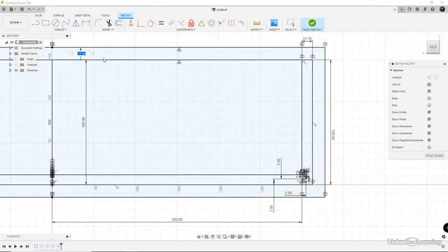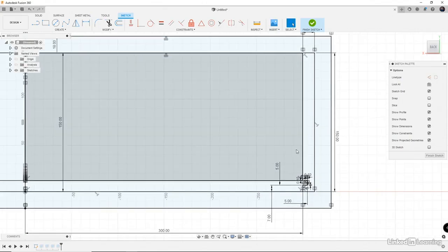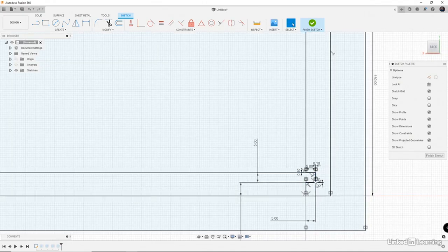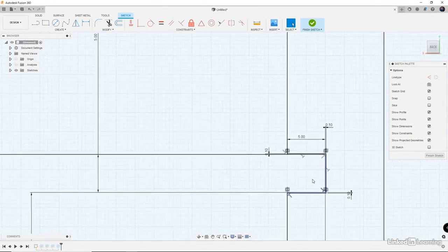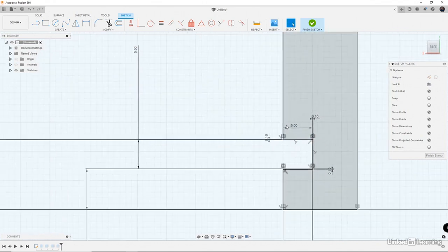When I have 15, I could do -18 and update the size of this to whatever I wanted. And then these are the sides, and then I built like a little dado, and then I actually made a little tolerance on the dado. So there's a little bit of slack. I think it's 0.1 millimeters I have right here. And then all of these dimensions are changeable.